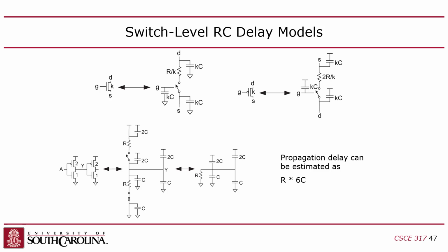And you might say, why 2C? Well, because remember, the PMOSs have a K of 2 at the least, at the smallest. They're double size, right? The pull-up guys are double size because the carrier mobility of the holes is half of that of the electrons. Make sense?